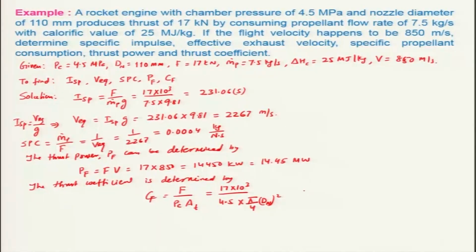That happens to be something like 0.72. So, you can see that it is a very low value, and you will have to take care of units, because if the force is in Newton, the pressure must be in Pascal, 10 to the power 6, and you can substitute d_n in meters and find this out.